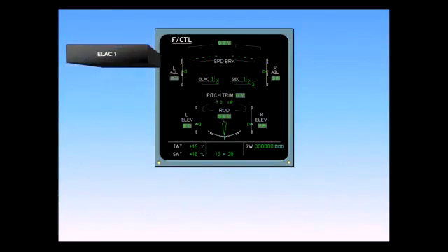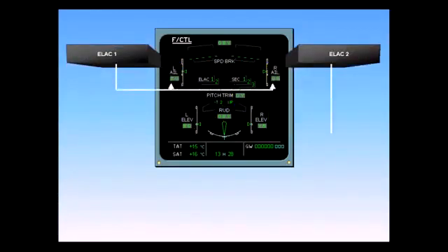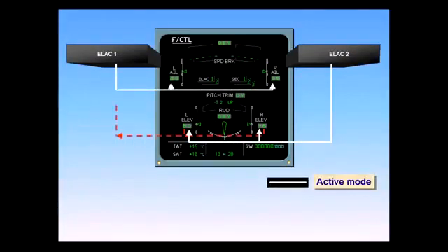Each actuator is controlled by a different computer. One actuator for each surface is always in active mode. The other stays in damping mode and is monitored by its associated computer.